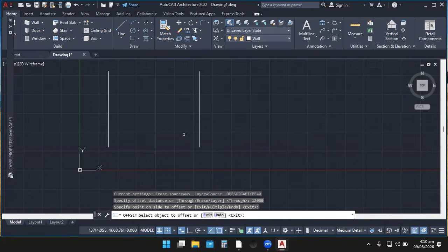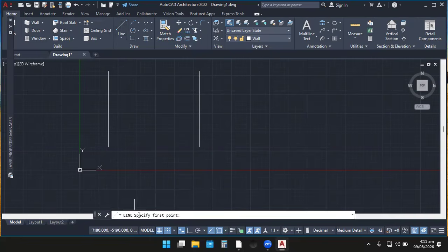You see, we want to build just a single room. So I just click a line again. I'm just going to cross it, or I can even start from one end. But if this is not on, you can't pick from the corner. You see, it will not be precise. So you always have to make sure that this is on, so it will always help you get the corner. Okay.